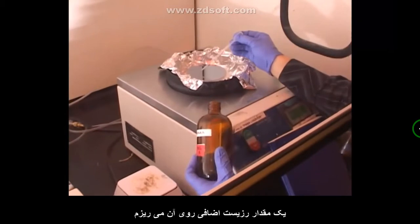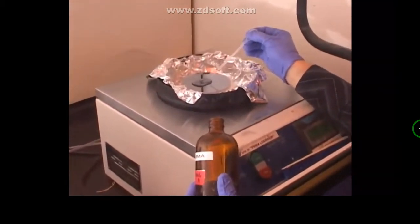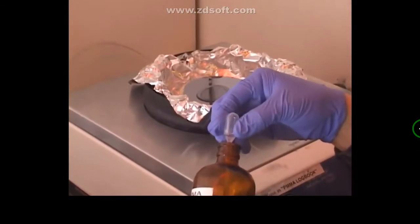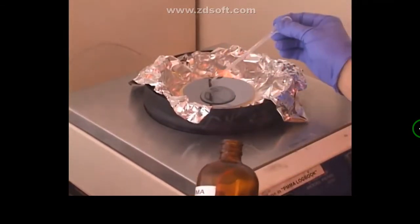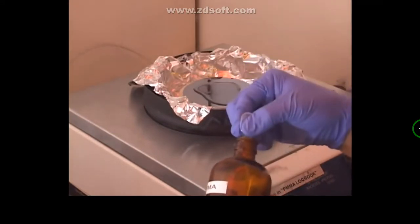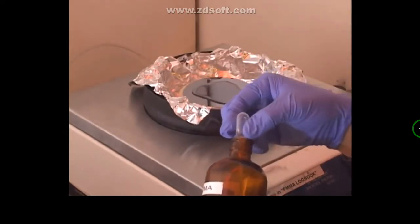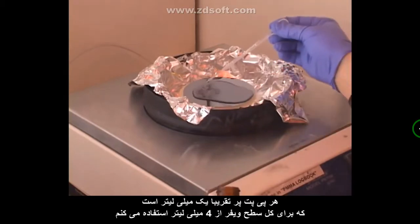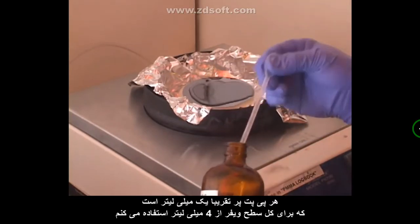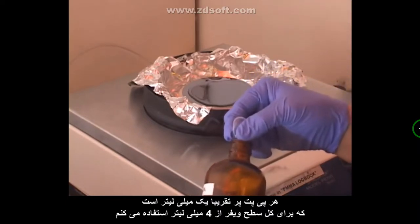I'm going to apply an excess of the resist. And the extra volume will all spin off into the bowl. Each pipette full is about 1 milliliter. So for an entire wafer, I'm going to use 4 milliliters.